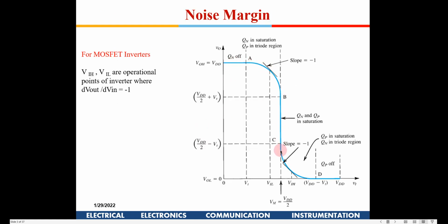So now this was the kind of slopes we started getting for the CMOS technology. Here, if you see, there was no band of VOH and no band of VOL. So let's first define noise margins here. Here we are assuming VOH is equal to VDD. Again, we'll see this is also not a necessary condition. VOH could be less than VDD, or VOL could be less than ground or more than ground also.